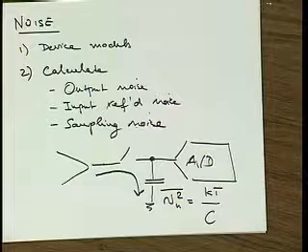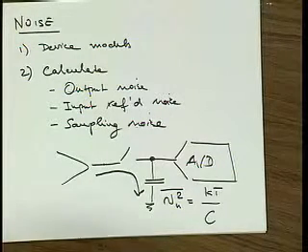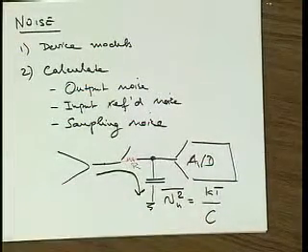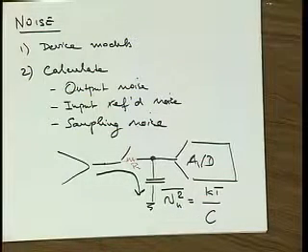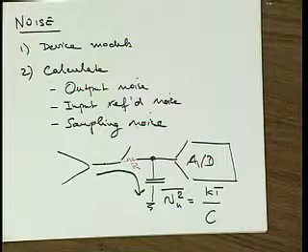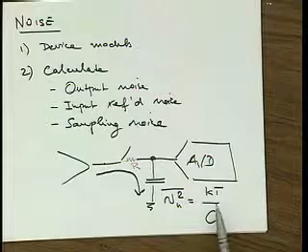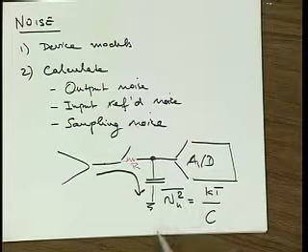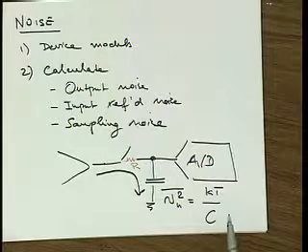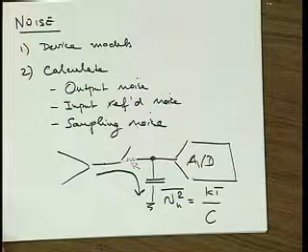And that result we calculated under somewhat special circumstances. We said, well, when the switch here is closed, it's really some kind of a resistor R. And we assumed that all the noise is coming from that resistor R. Okay? And then, surprisingly enough, we found that the total noise, or the variance of that noise, the noise that we have on this capacitor here, of these noise samples on this capacitor, is not a function of the value of that R, it's entirely a function of that C.